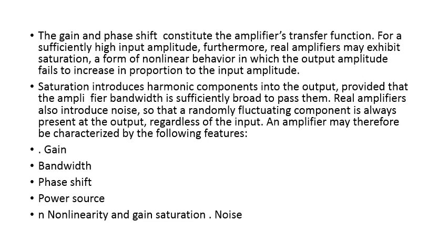Real amplifiers also introduce noise, so that a randomly fluctuating component is always present at the output, regardless of input. The amplifier may therefore be characterized by the following features: gain, bandwidth, phase shift, power source, and non-linearity of the gain situation. These are the factors used to characterize it.